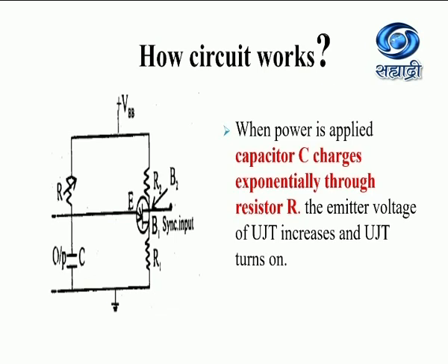If you consider this circuit, there is one UJT, with two terminals B1 and B2 as the bases, and the emitter is connected to the capacitor. In that circuit we have one variable resistor, R, and one positive power supply, VBB, connected to base 2 of the UJT. The output of this circuit is across the capacitor. That sawtooth waveform is basically the charging and discharging output of the capacitor. By using this UJT we can charge and discharge the capacitor exponentially and we will get the sawtooth waveform.